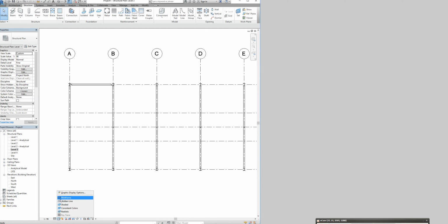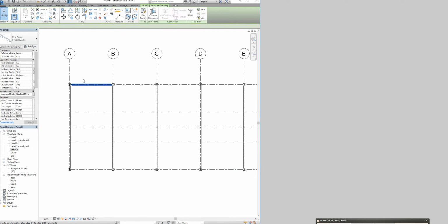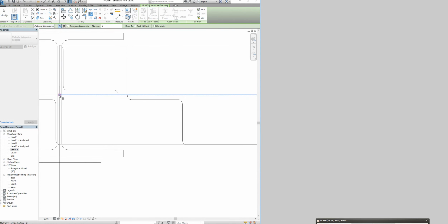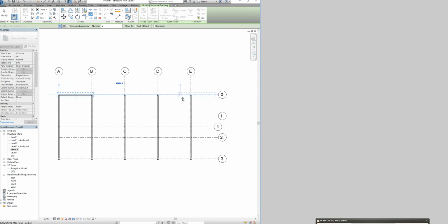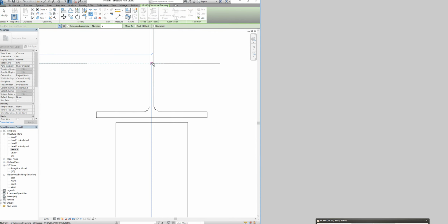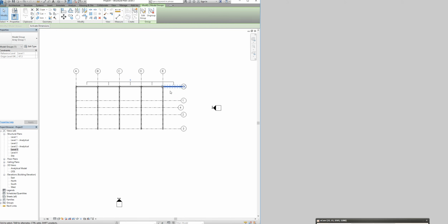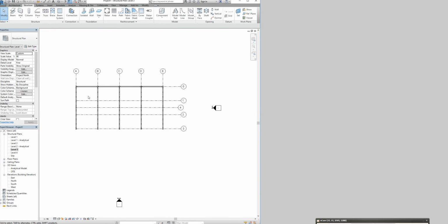So all I did was, it was in coarse. So I changed it to fine detail so I can see the slides. I like to work in hidden line. So we're just gonna select the bracing. Remember that it's 2 bracing, not only 1. Array. And then we go from here to here, right? How many repetitions? So 5. All right, actually we only need 4, so that's fine.